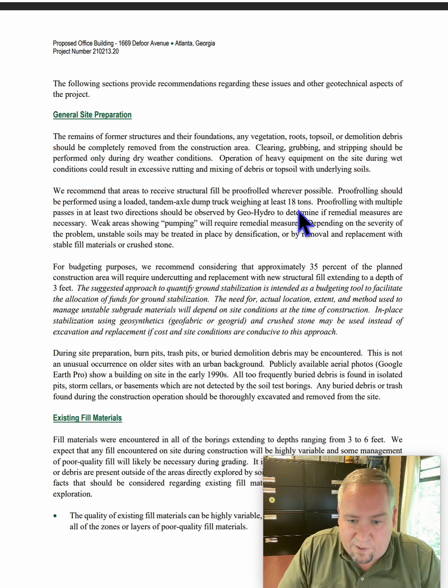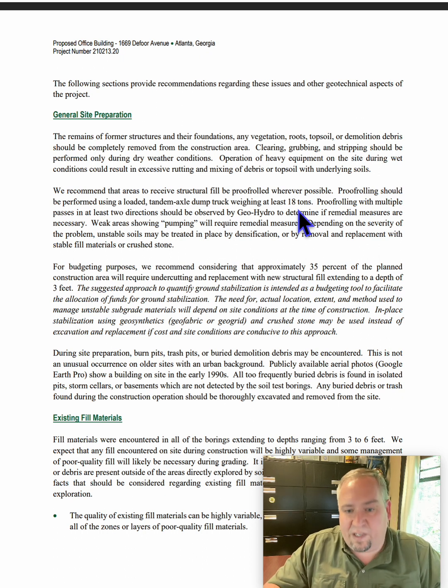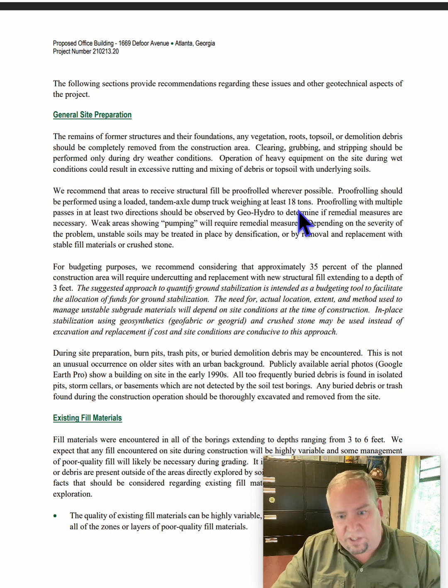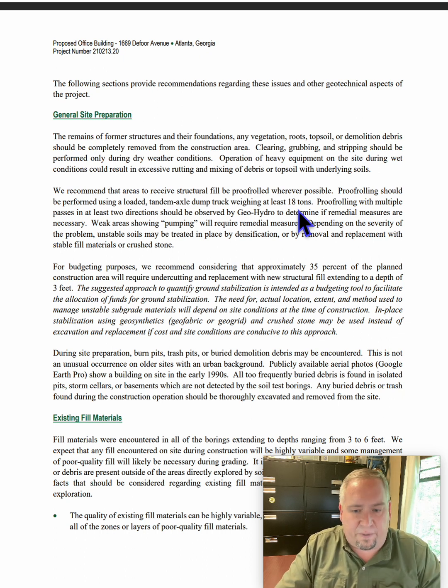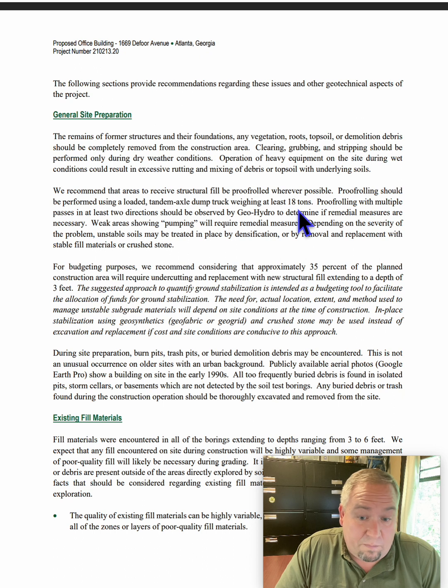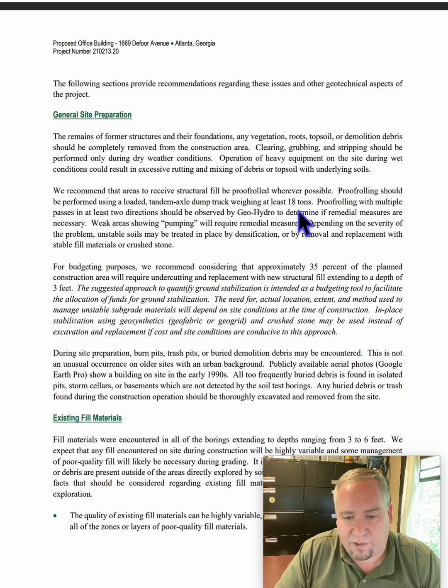And they're going to be looking for what I call mattressing or pumping or settling or squishing or anything like that before anything is filled above that. Again, you can put a slab of concrete on top of a mattress, it's still going to wiggle. So we want to make sure our base is tight, and if there's any problems, let's remediate them, fix them before we start placing fill. So they're recommending a proof roll and all that.